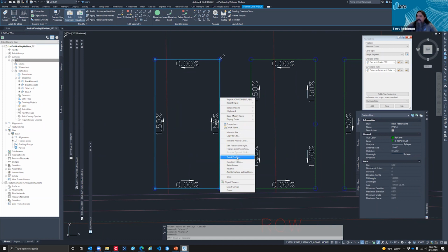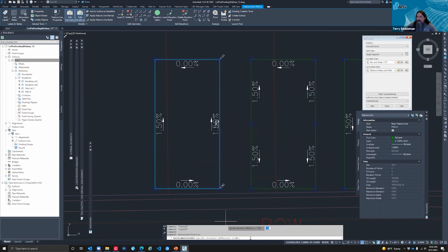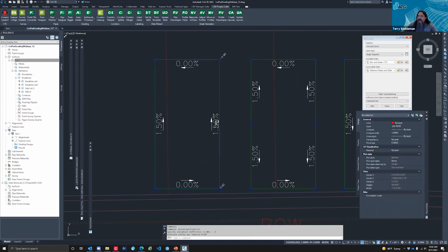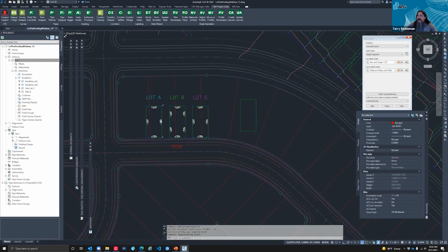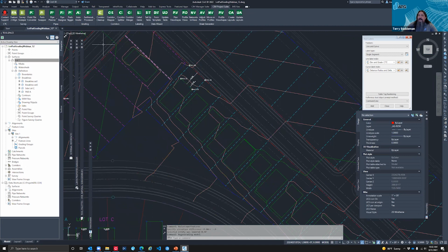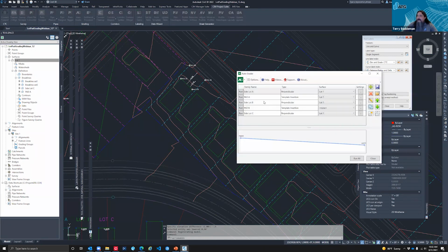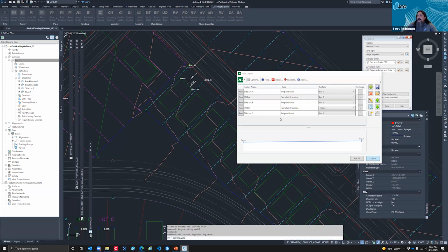So I'm going to go ahead and put in negative 0.9 and drop that down. So now my elevation's at 0 here and at 0 here. And then we'll rerun this grading family and see what happens with our slope. So pad A, and then we'll rerun this guy, and it should fix our elevations here.